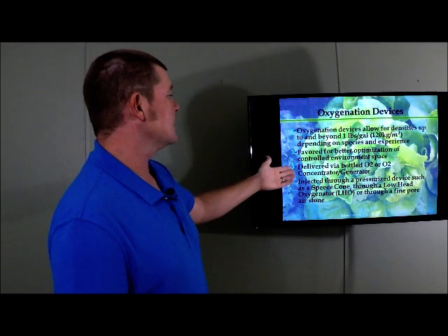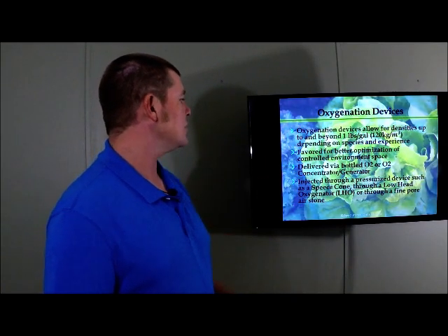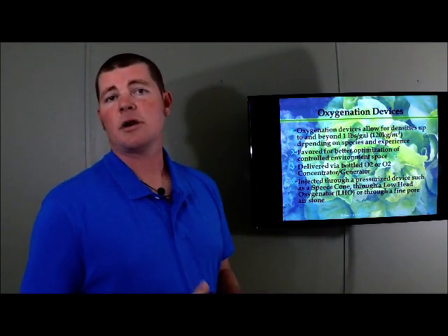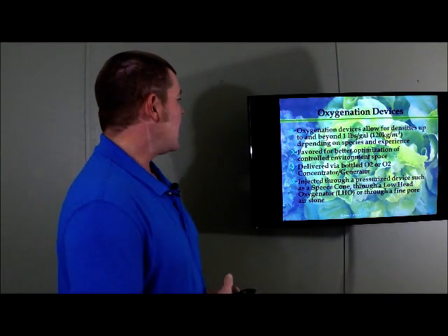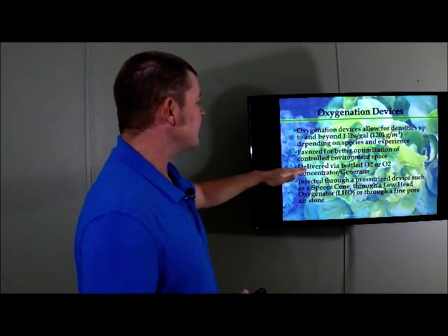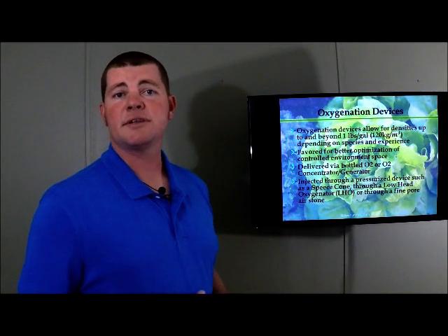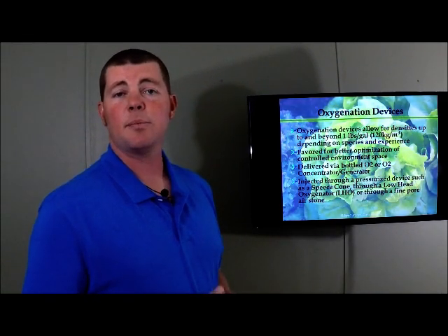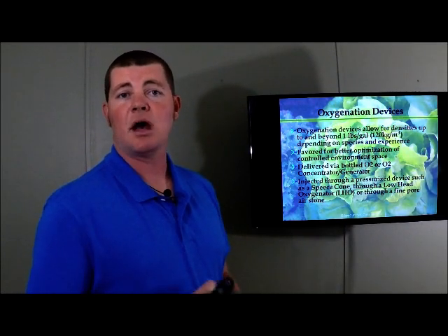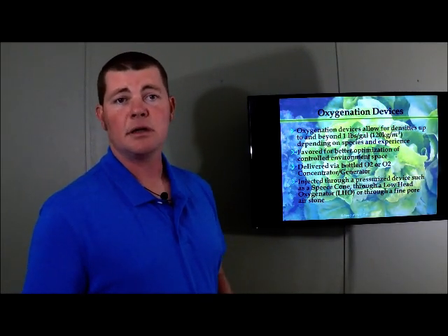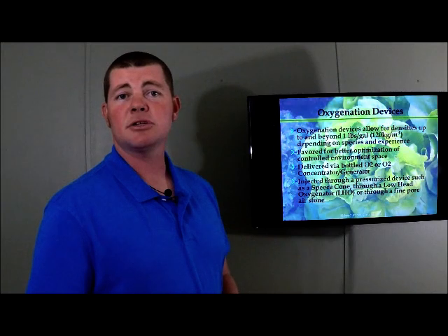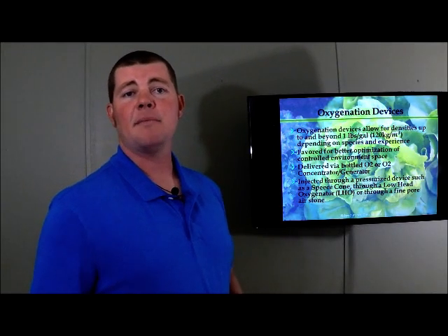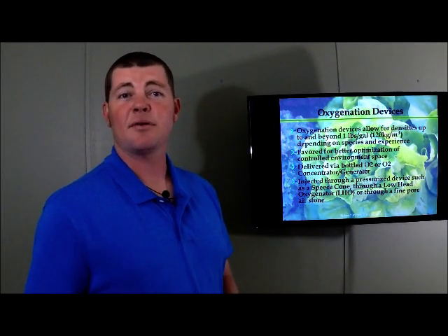Again, the oxygen is delivered via bottled oxygen or oxygen concentrator, oxygen generator, which means if it's delivered by a truck, usually you have an on-site tank that you will have the oxygen supply company fill up, and you run your main lines off of that into your facility. You sign a contract with the oxygen supply company and you have them on a fill contract so that you never run out.